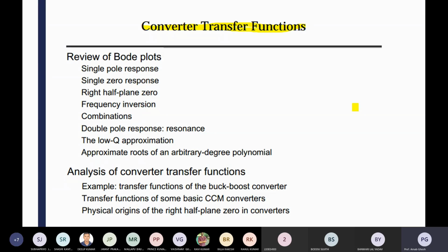You are giving some reference input to your system. If you give a disturbance, meaning an additional value on your reference, that relates to reference tracking. Reference tracking means you are giving a reference voltage or a reference current to your system, and now you add a step value to your reference. If your converter is working well in closed loop, then your output always follows that reference value.